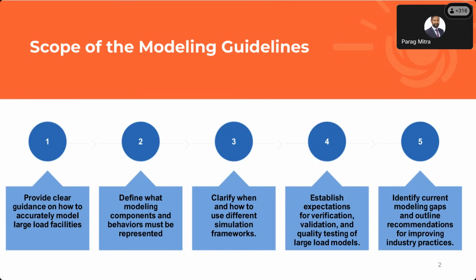The fourth piece that we cover in this particular guideline is to provide guidance on how to validate models and verify the parameters if these models are being submitted to you or if you're responsible for developing these models. And then having some sort of a model quality testing protocol that allows a transmission planner or a utility or an interconnection authority to make sure that the models that are being provided to them are actually good enough to run the study at hand, whether it be an interconnection study or